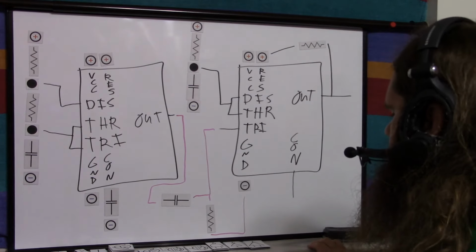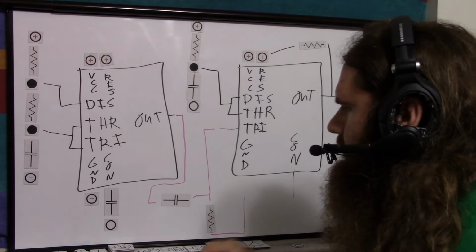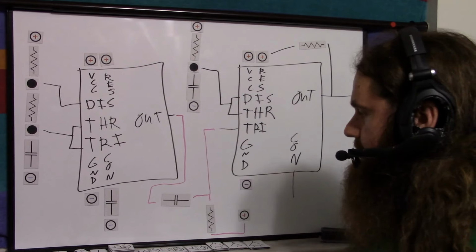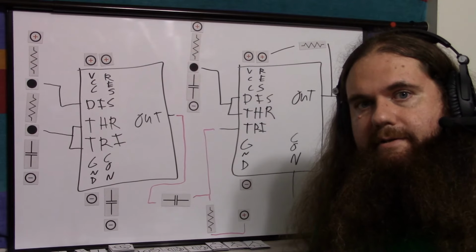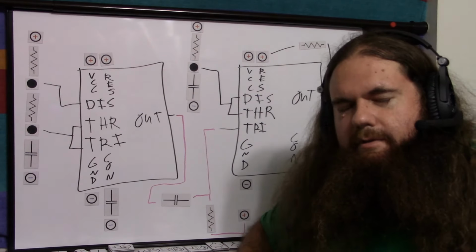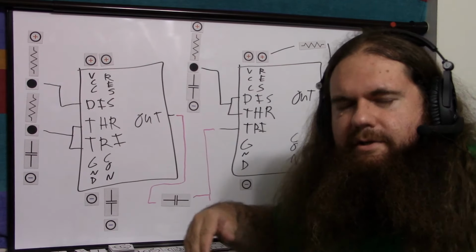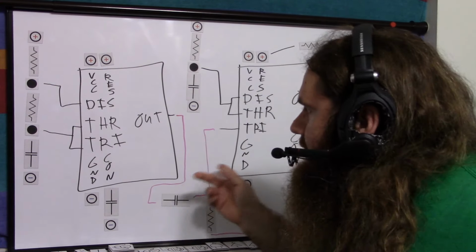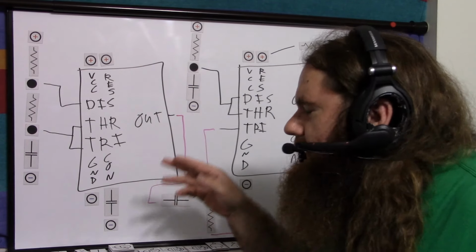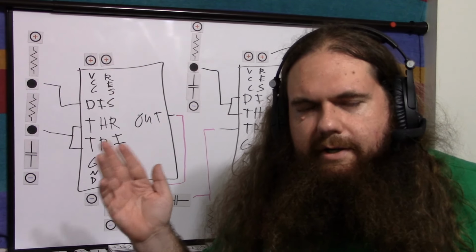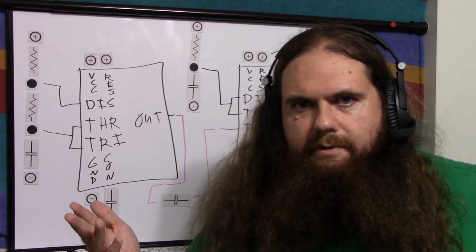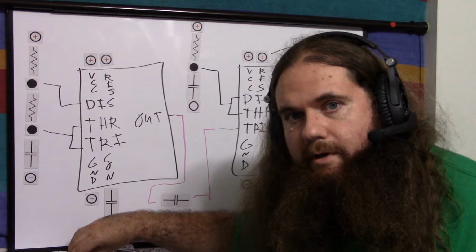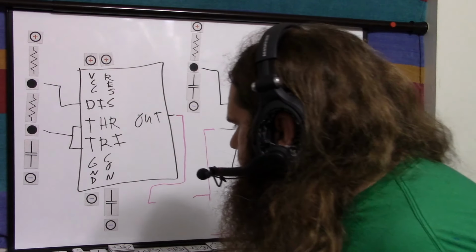Now, there was another way to hook this up. Instead of hooking it to negative, we hook it to positive. So it's still a high-pass filter. Basically, we just biased it. The problem is we biased it with the full 5 volts in that case. So now we've got a 2.5 to 7.5 volt signal. Now it's not going low enough. So I fiddled around with this. I tried to make it work. It was just plain stupid. Bless the internet's little heart. But sometimes they are thinking too hard, and they had me thinking too hard for a while as well.